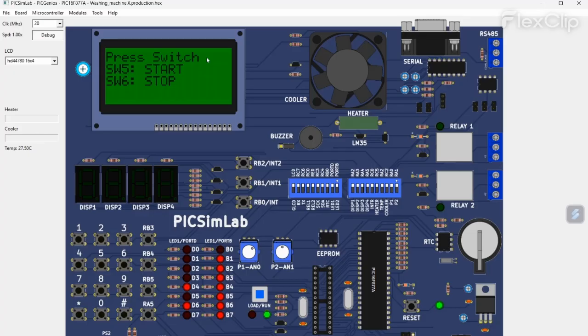If I press switch 6, what will happen? You will directly go to the main program screen. For demonstration, I am pressing switch 6, which is RB5. See, we have already gone to the main program screen, with programs like rinse, dry, wash only, aqua store, daily, heavy, and etc. Now I am again selecting stain wash by long pressing switch 4.